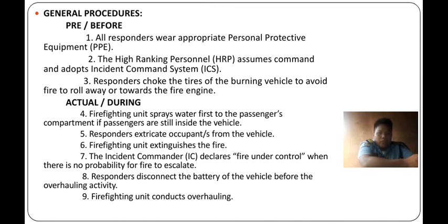4. The firefighting unit sprays water first to the passenger compartment if passengers are still inside the vehicle. 5. Responders extricate occupants from the vehicle. 6. The firefighting unit extinguishes the fire. 7. The incident commander, IC, declares fire under control when there is no probability for the fire to escalate. 8. Responders disconnect the battery of the vehicle before the overhauling activity. And 9. The firefighting unit conducts overhauling.